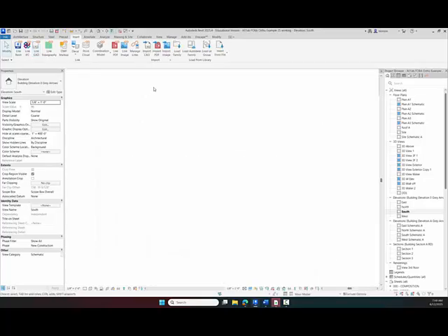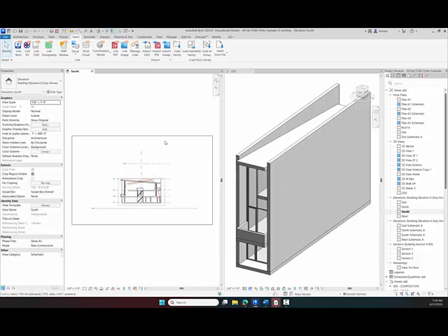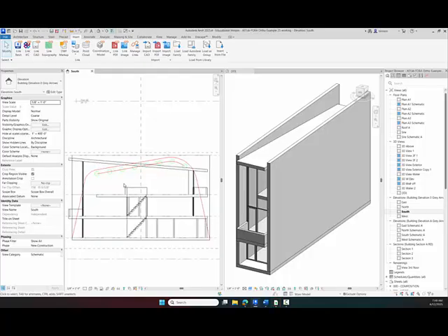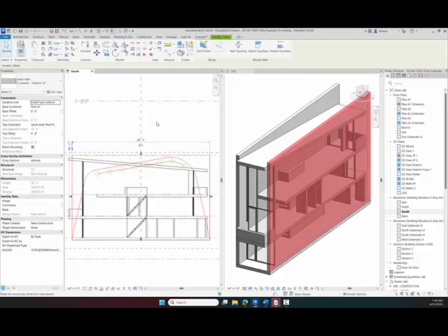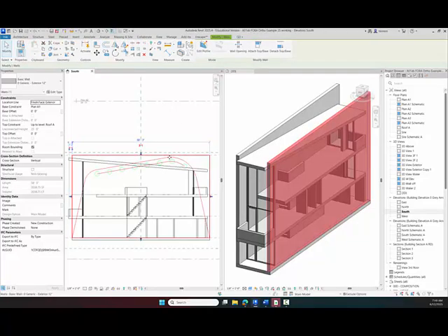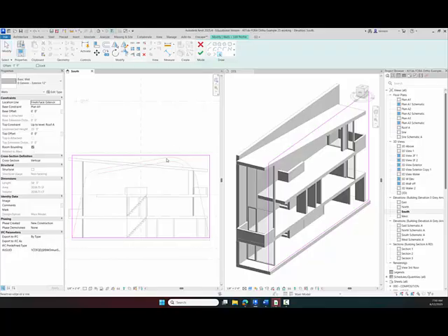And then what I'm going to do now is do my little 3D thing so you can see what's happening in 3D. If I come in here and pick the wall, one of the walls, it doesn't really matter which one, I can edit the profile. So again, that is select the wall and edit the profile up here at the top, and then go to the pick line. I can do one of two ways.